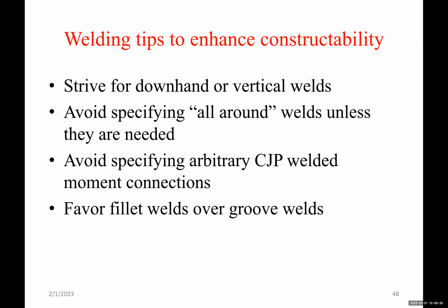Okay, and then what's the typical tolerance or gap for that? As I said, plus I would say ½ inch; that typically would cover any issue in terms of conflict that you may have in the connection.